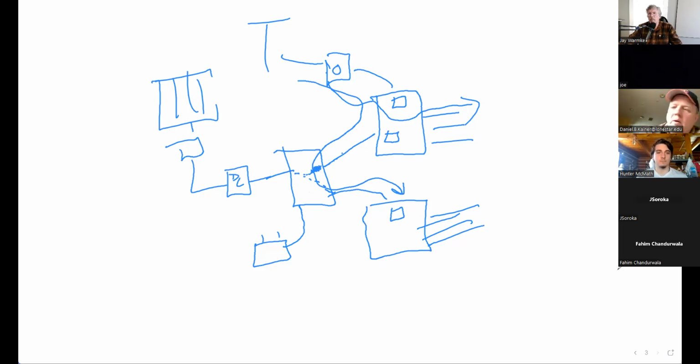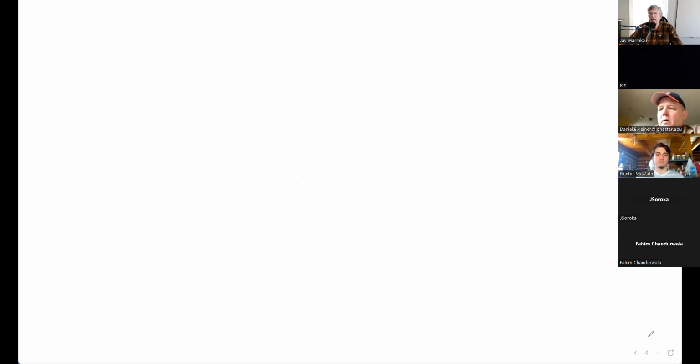Okay, now one of the newer things that we're dealing with a lot, let's see if I can get this pen all the way down here, is a system that I'm just about to install here at our office. I'm going to use a microinverter system. So when you're using a microinverter system at the array, you've hooked up little microinverters to each one of these panels. So the output from the array is not DC, it's 240 volts AC. Right? So all the way right from the array, we're only dealing in the world of AC.